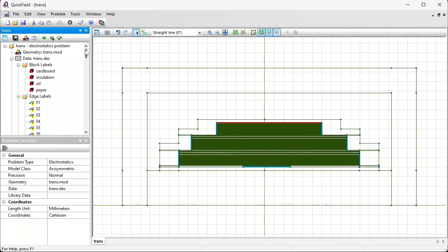Okay, now what about the winding layer 1? The left end is grounded. There are 430 turns in this layer. Electric potential is distributed linearly.